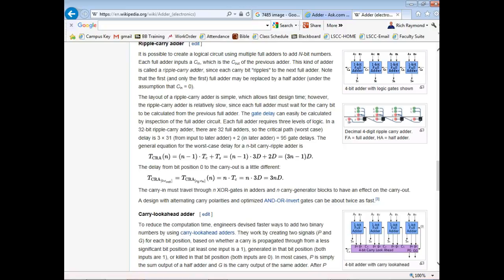We touched on that a little bit. They talk about hexadecimal arithmetic. That's real fun, because you carry on 16. But once you learn how to do it, it's not hard. Then they get into full adders, half adders, and the IC that they talk about is a 7483. So it's an adder.